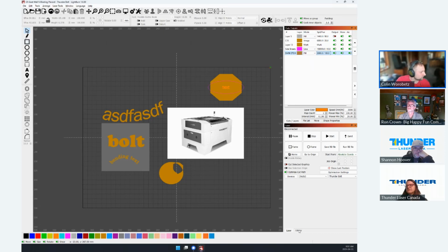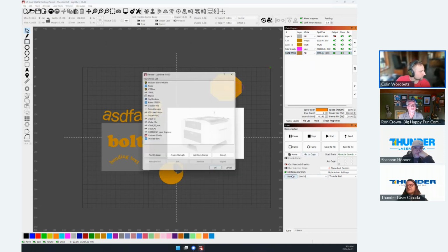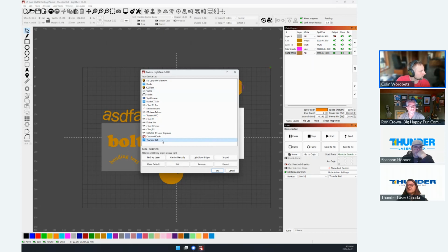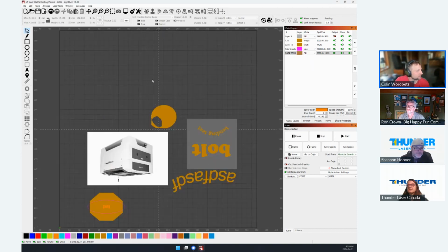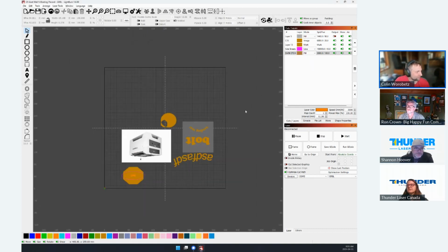How do I show you from, go to devices? Let's look at Thunderbolts, Ruida. So when you set your axes lengths, there will be this. Where is your X0, Y0? And so wherever your machine homes to when you turn it on is going to be where you set this. This should be only set up once. And so you can see I changed it, and now my orientation of everything changed because my 0 point flipped.